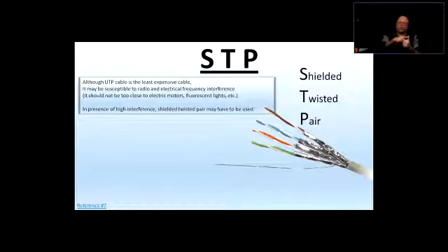The worst things are thermostats. They are huge noise producers. Security alarms and fire alarms are next, and then there's the HVAC control systems as well, and fluorescent lights. They can actually kill your transmission. Right? Now, when it comes to unshielded twisted pair, when you have a lot of interference, sometimes you have no choice but to spend more money and install shielded twisted pair.